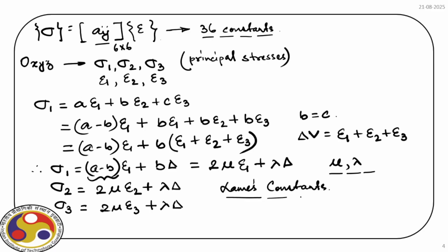Okay. So the first thing to remember is that if the material is homogeneous, elastic, isotropic, then we can correlate stress with strain using two different constants. Now, if you recall your elementary strength of materials, we are familiar with Young's modulus. In fact, the 1D case I showed you in the previous slide had sigma and epsilon related using this constant, called Young's modulus, right?